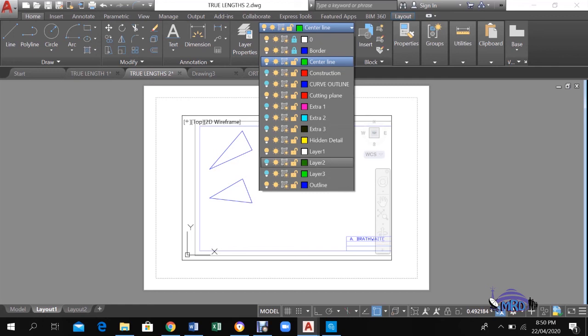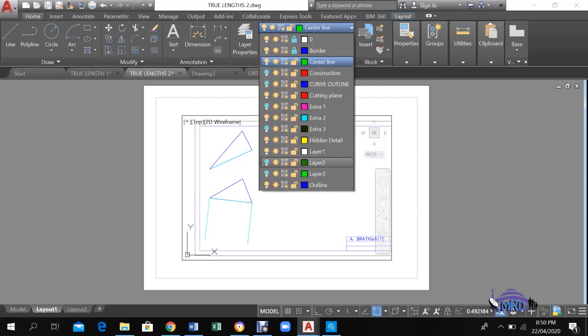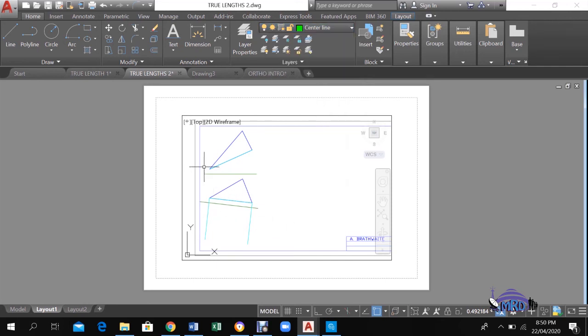The third side, we will use the auxiliary method, where in this instance I've highlighted again the 2 sides, and you know that you would project the lines at 90 degrees. You know that you will definitely need to have the XY line in position. So I've dropped in the XY lines and the corresponding XY lines so that you can see.